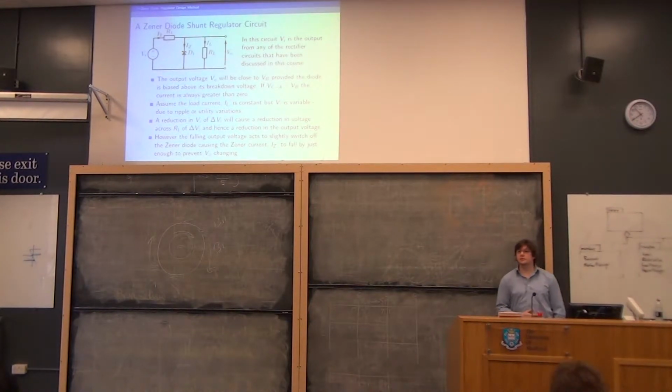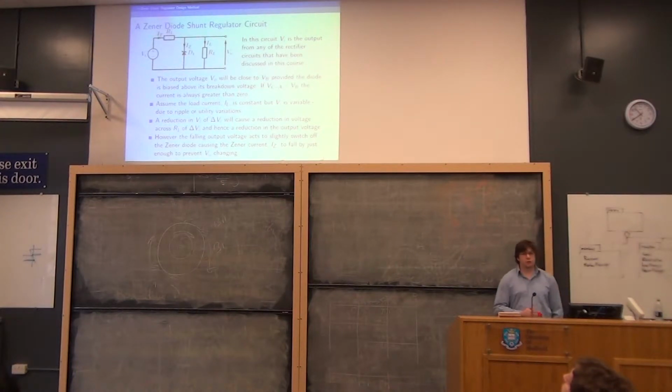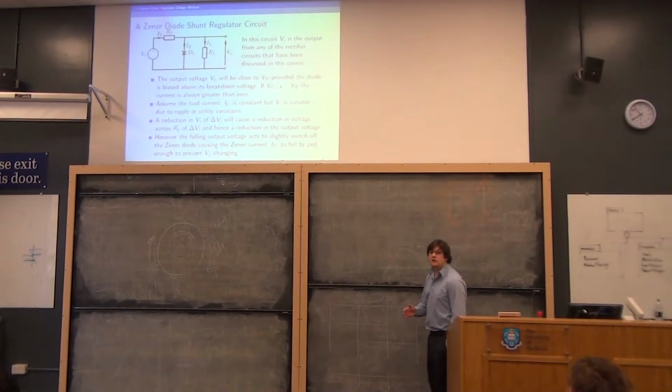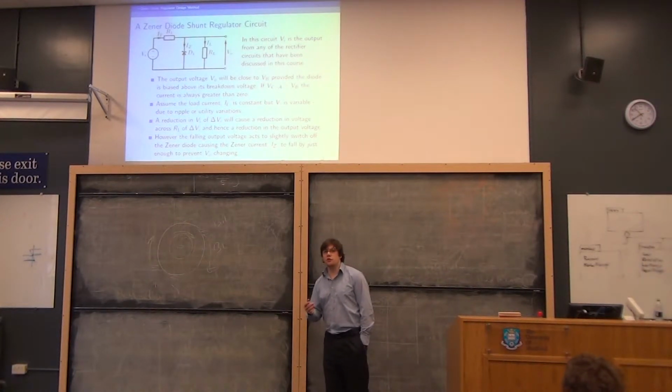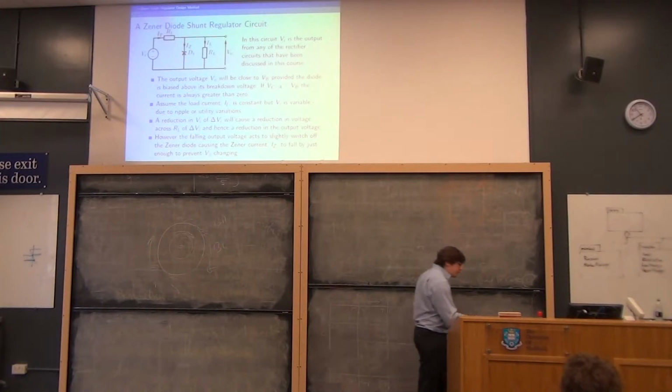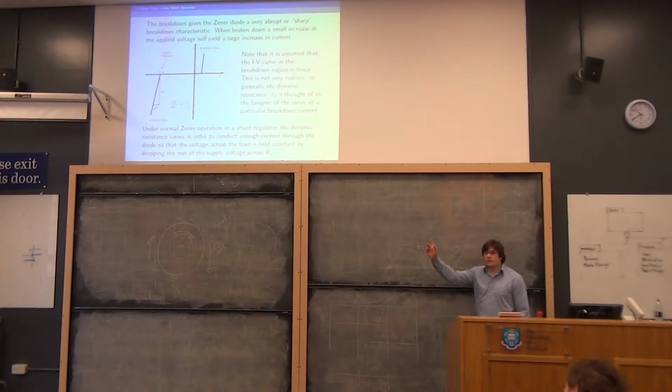You might think that's true. If we assume there's no Zener diode, it's definitely true. But the falling input voltage causing the output voltage to fall slightly causes the Zener diode to conduct slightly less current, because its cathode to anode voltage has now dropped, and we will be moving up this line.